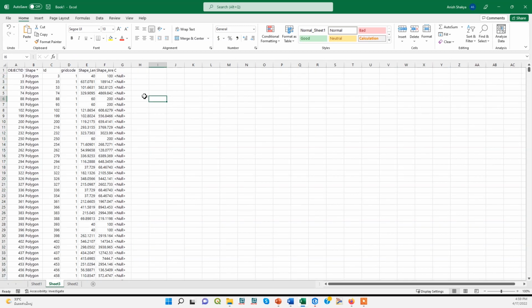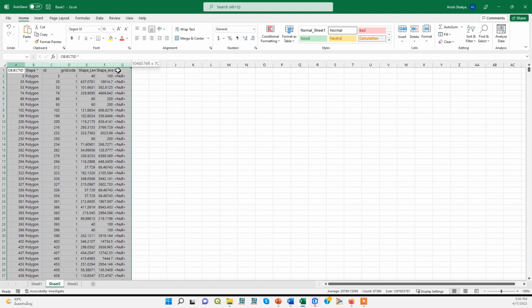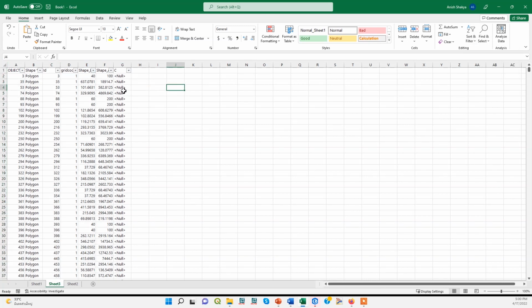Paste. Okay, so what we will do now is, for each grid code or each land use land cover class, we will be putting the values. There's an easy way: we can first filter it, and the value of C is obtained from different literatures. These references can be seen in this slide.